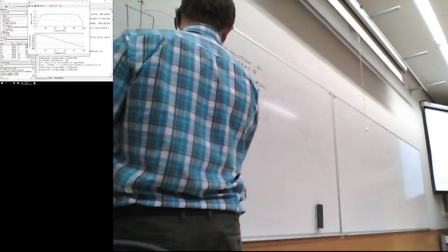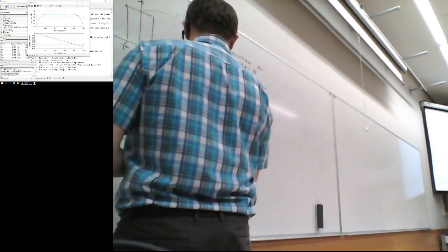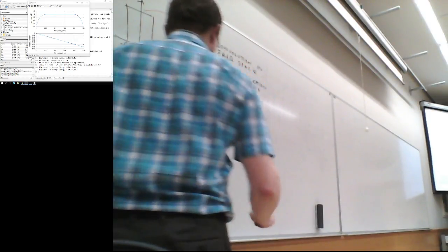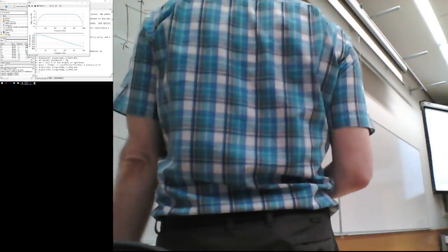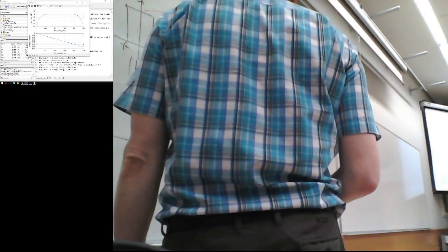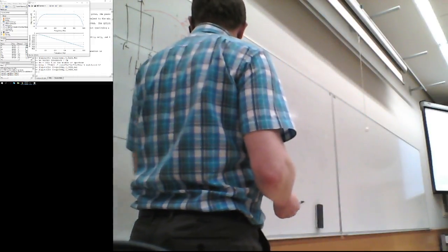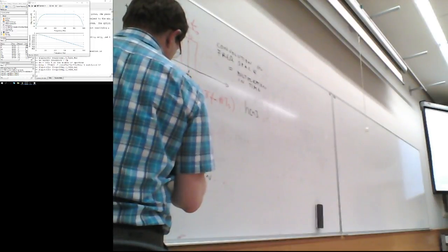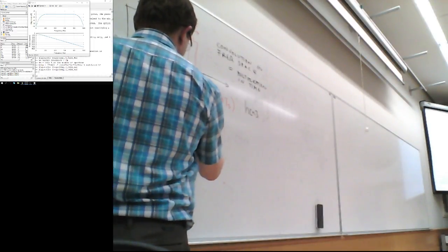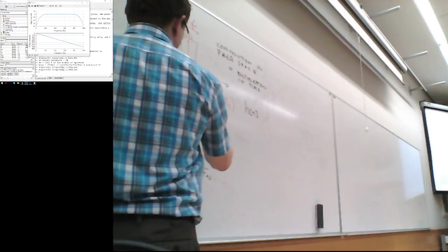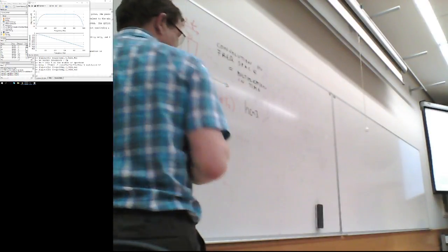Low pass to high pass. If you set this modulation frequency the same as the Nyquist frequency, you actually get a filter transformation from low pass to high pass, so that the high pass filter full bandwidth is the Fc.